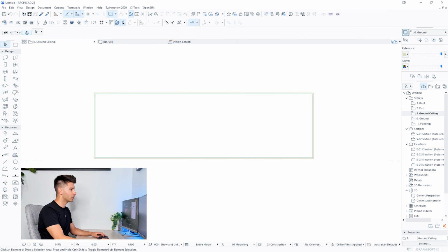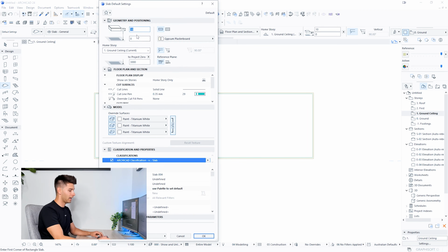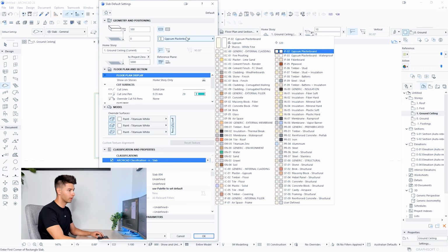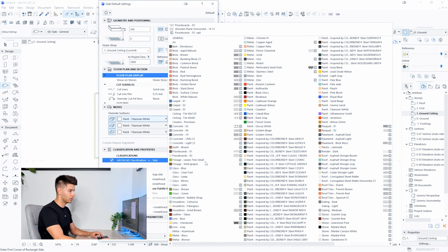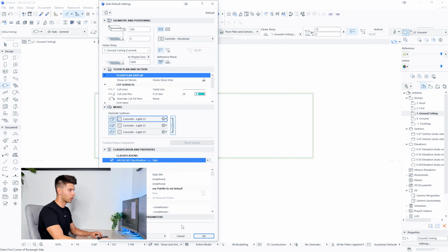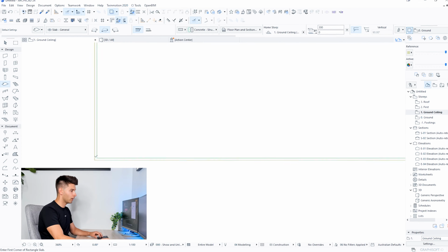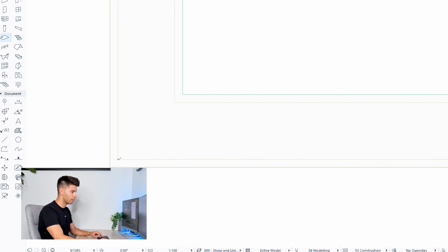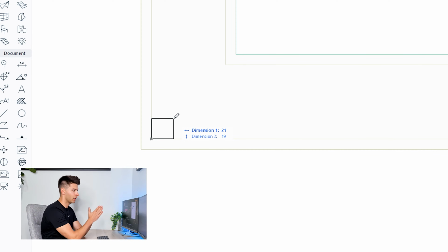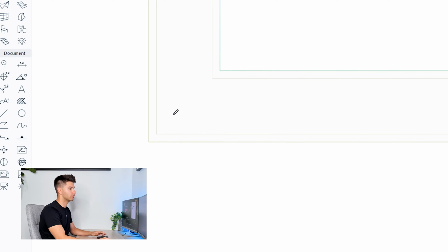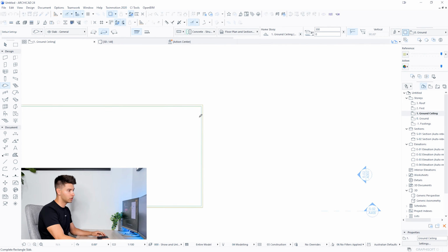So what we also want to do is include a new slab. So let's say we go back to the slab tool and we want to have a 300 mil thick slab. We don't want it to be plasterboard, we actually want it to be concrete. So we find where the structural concrete is, click on that, change that back to the concrete that we used before, concrete light 23. And what we actually want to do is zoom in to the corners and find where the plasterboard separates from the wall material so we can run our sheet beyond.